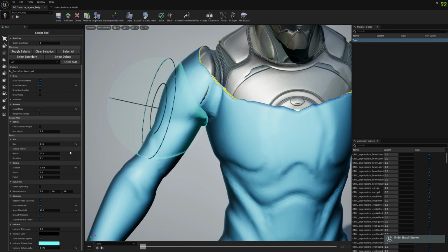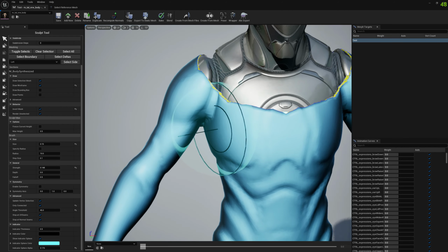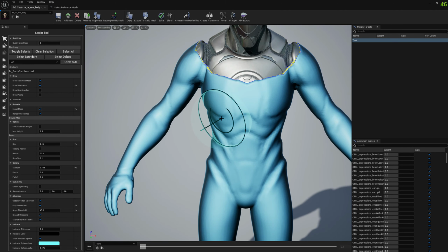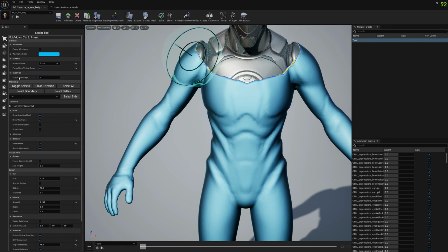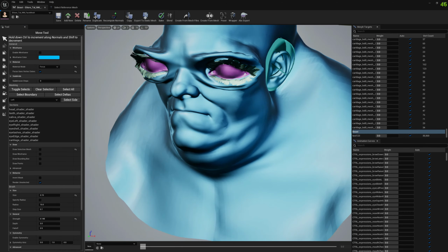So let's see. Kind of like this, right? Okay, and again, if you want to see how sections intersect each other, go to material mode and select focus, and focus uses vertex colors, and it will show you each section with its own color. Otherwise, if you keep it selected, it's the default sculpt material, right?